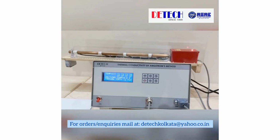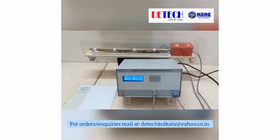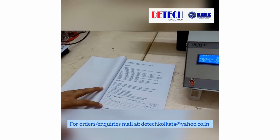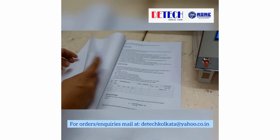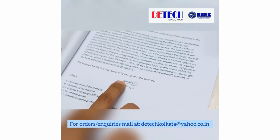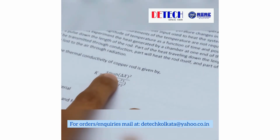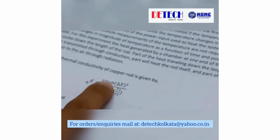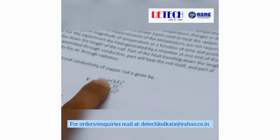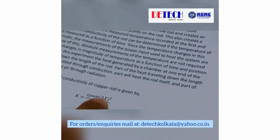So like this, heat pulses are given at an interval which is specified by the T on and the T off timer. We have to account the number of pulses over a period of time for calculating the thermal conductivity of copper. The formula used is this, where S is the specific heat of the material, that is copper, where ρ is the density of copper, where omega is the angular frequency which corresponds to 2 pi f. Where F is equal to 1 by T and the T is given by the addition of the off time and the on time. And del X is the distance between the 2 temperature sensors.